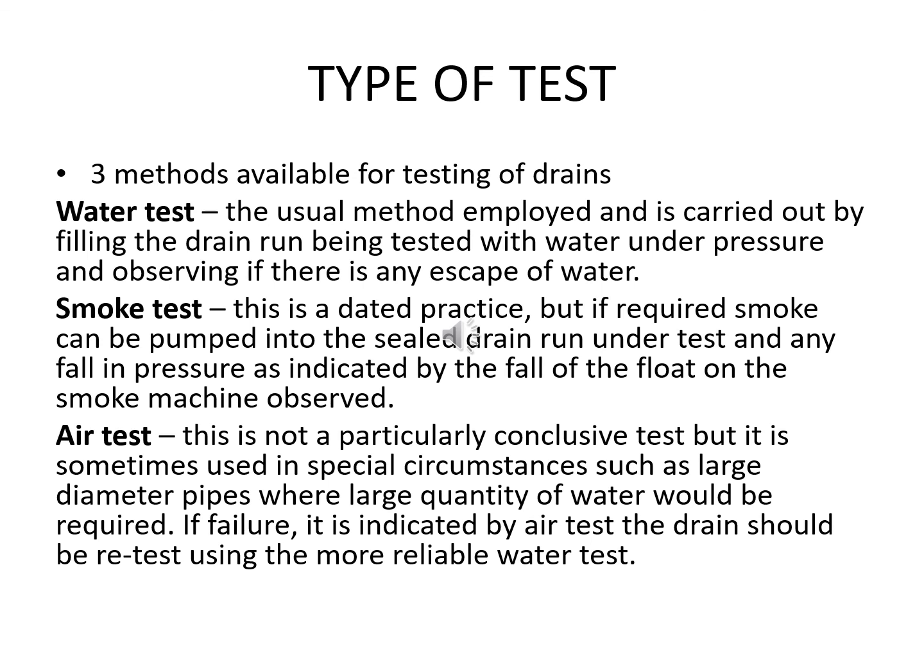And finally, the air test is not a particularly conclusive test, but it is sometimes used in special circumstances such as large diameter pipes where a large quantity of water could be required. If failure is indicated by the air test, the drain should be retested using the more reliable water test.